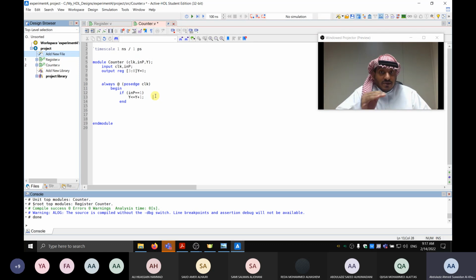If there is a limit that's asked of you, like I want to count from 0 to 10, maybe, I don't want to exceed that limit. Of course, you'll modify the code. If it reaches that limit, it goes back to 0. But here I have a natural one. After it reaches 15 once, naturally it goes back to 0 if you add 1 because of the overflow. So nothing like this here. So Abdulaziz, Fahad?